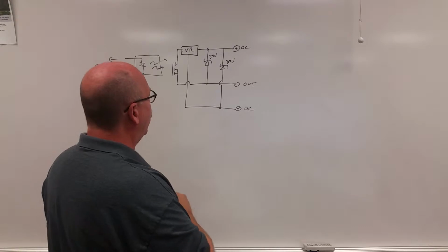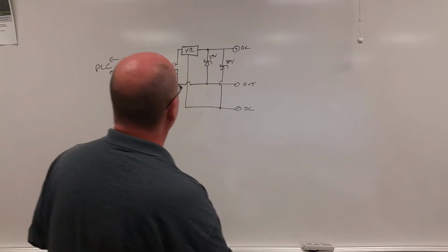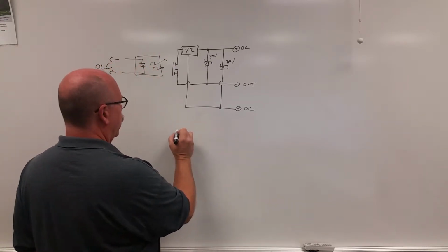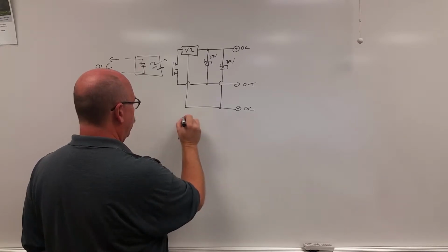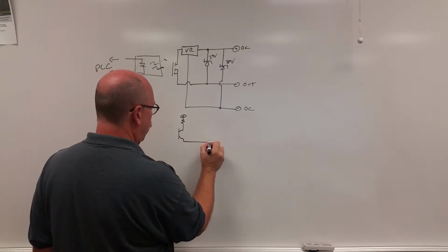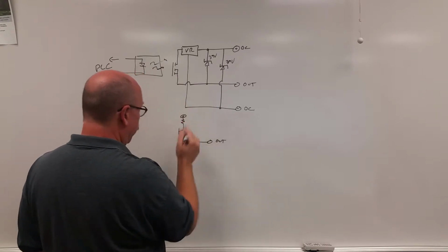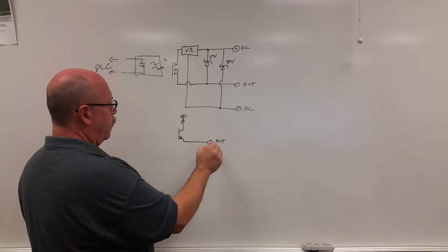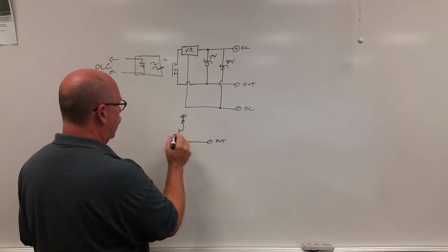So let's talk about why they use a FET rather than a transistor on the output. Typically, transistors, when set up as a source, which would be in this manner, which is going to be the output, I'll use an NPN. Since the transistor is sourcing the voltage out, this NPN is technically called an emitter follower.